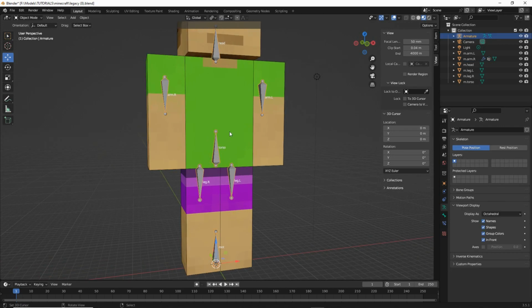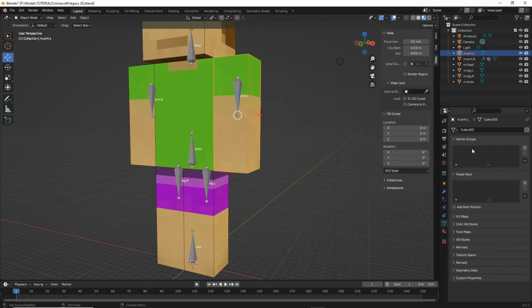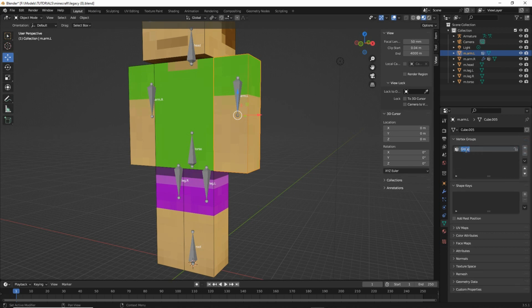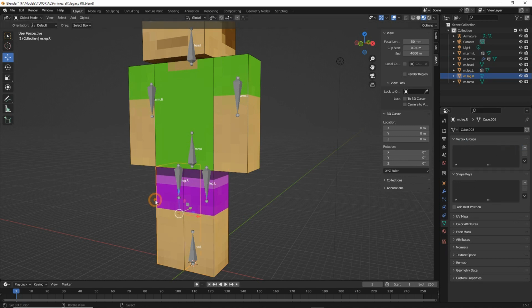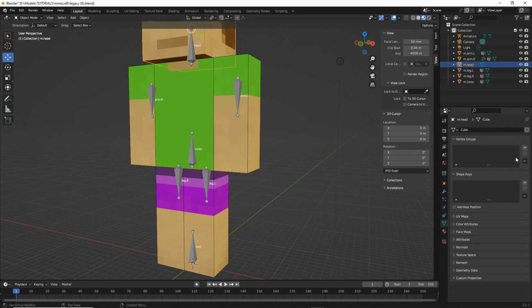So it's armature object type, mesh object type, and then bone element to mesh element. And all we have to do is repeat that for all the other parts. So object, new group, double click, arm.l, new group, leg.l, new group, leg.r, new group, torso, then new group, head.